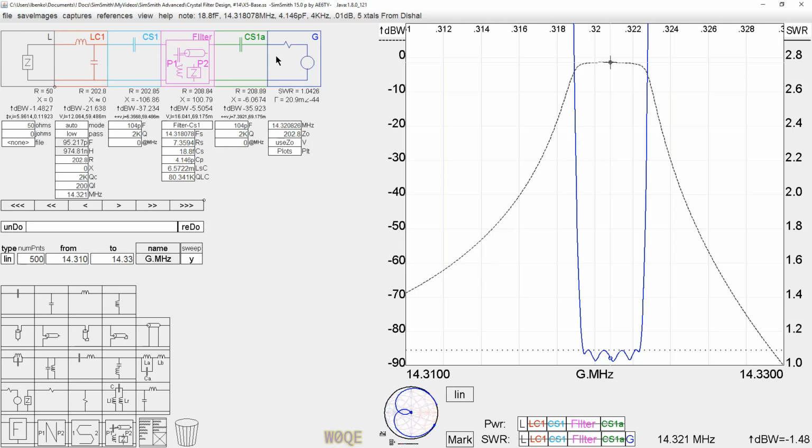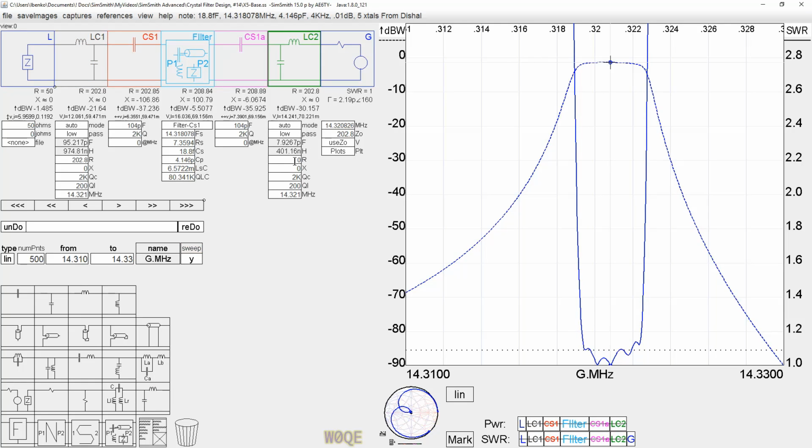And let's follow this circuit with another one on this side. The one on this side needs nothing done to it because it'll match to 50 ohms. It'll match to 200 ohms as it is. But what we want to do is force it to 50 ohms. Now we can either put a 50 in here, but then we won't read SWR properly, so it's just easier to change our generator type to 50 ohms now. This will adjust itself, and here we are. Not quite as good an SWR as we had initially, but it's pretty close. We have some problems in doing this in that this is matching at one frequency only in this range, and there is loss in these inductors. But this is still a very good SWR here.